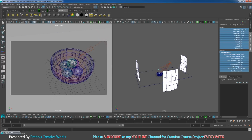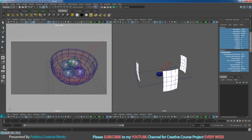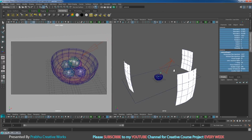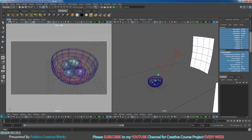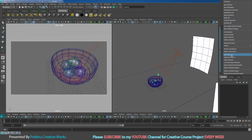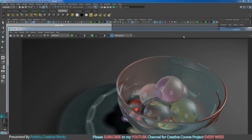Now I will set my camera view like this, a little bit closer. Now go to view, select cam. I will select all the attributes in my camera, right click and choose lock selected. I will select this view and click render.